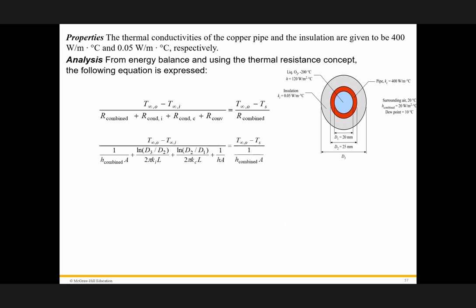Good. Therefore, now we look at this equation, we have all the numbers. The only thing you have to remember, this is the exterior surface. This is outside. And this here is Ai. We go back. Area for outside is pi D times L. This is perimeter times the length. This is D1 L, this one, and this one. Please put Ao outside here, and this one is interior.